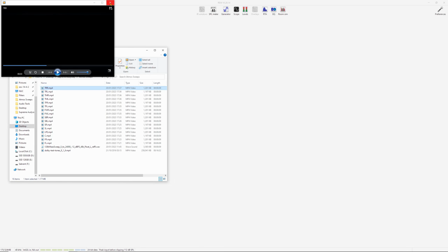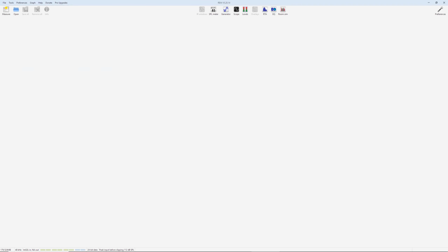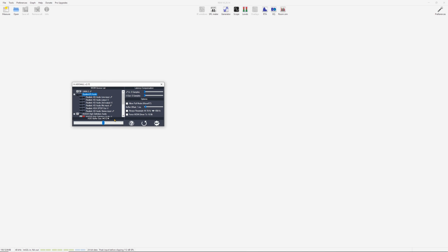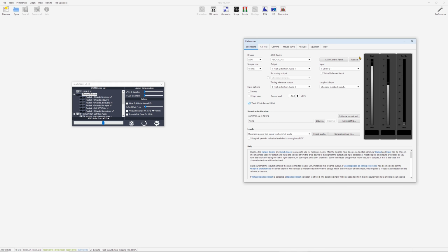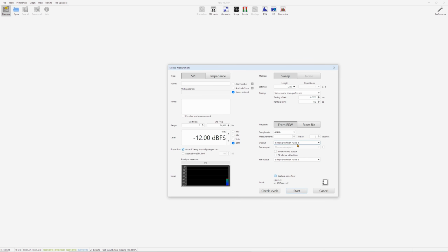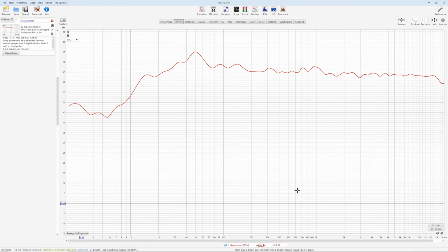Because now you have to remeasure every speaker, now that they are supposed to be corrected, and they will be. Let's try a couple of them. I will do from REW sweeps, reload, measure run for the front left. The important point is that the microphone doesn't move and the receiver volume doesn't change throughout the calibration. I remind you one more time.